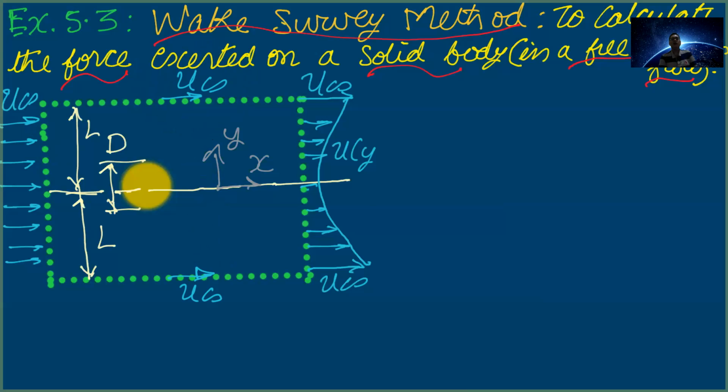While solving by momentum analysis, for many problems we have to use mass conservation. So whenever you take a control volume and solve momentum conservation, first make sure that mass conservation is obeyed. If you don't do that, you may make a mistake and solve the problem wrongly. You can miss that the x momentum flow rate is leaving from the side walls also, which in fact is the key to the solution of this problem.